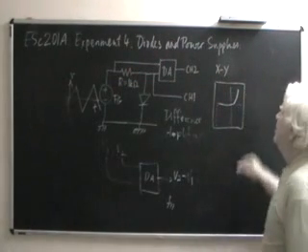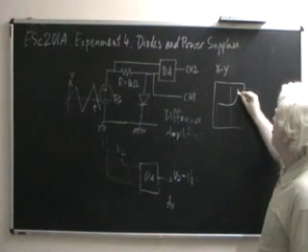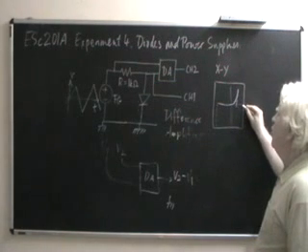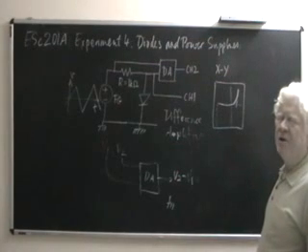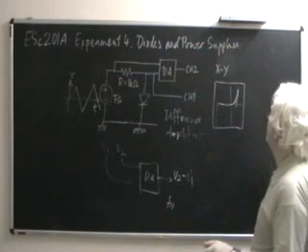the forward part. Now it's already been explained, it's going to be explained to you that you take a tangent of this curve over here, see where it meets the V axis, and that gives you the cut-in voltage, V gamma. All that will be explained to you by the people who carry out the experiment.